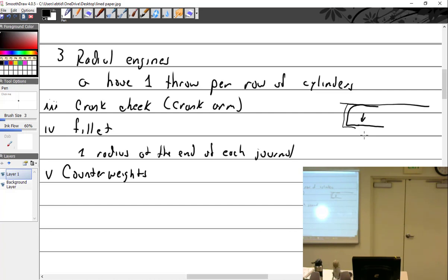So you actually inspect this area down here. It can't have any wear. It's not supposed to slap the crankshaft. They're actually being slung out, so it shouldn't be touching. If you roll it, you can feel it rolling back and forth like that. So this bump area, you inspect it, make sure there are no bumps there. There are limitations on how much damage can be there.